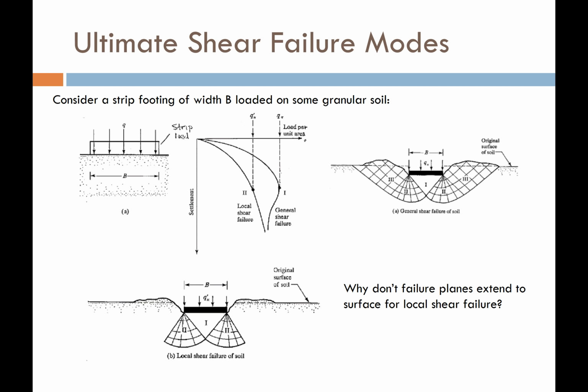Now there are two general types of shear failure that we could see in bearing capacity. Suppose that I had a really dense sand. What I would tend to see is, as the footing began to settle, I would see an increase in strength, but eventually it would peak out and then I would begin to lose strength. In other words, it begins to soften as it settles more.